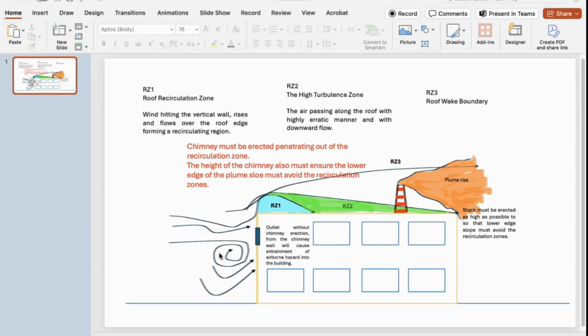I mean, higher efflux velocity is not a substitute for better plume rise, but it will definitely have a lot of better impact to fight erratic turbulence, or if your factory or your chimney is situated in a region where the wind velocity fluctuates, sometimes low, sometimes high.